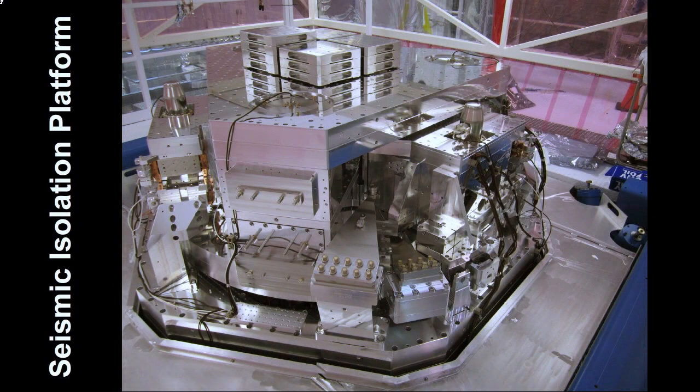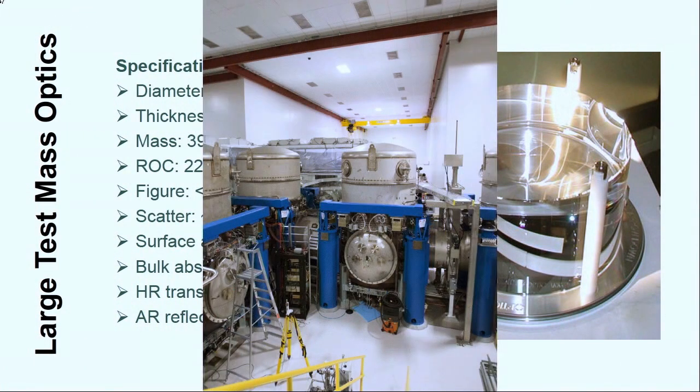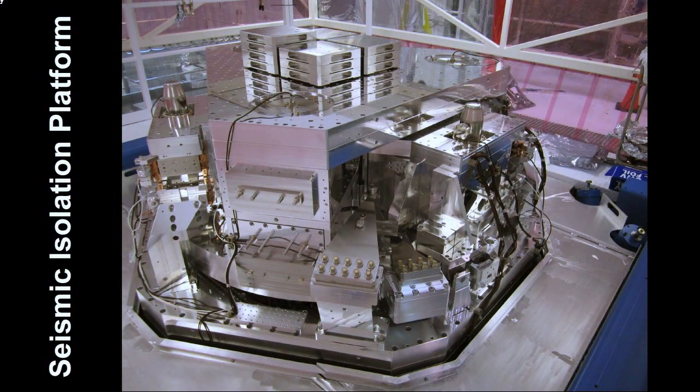This is a seismic isolation system. This quadruple pendulum is not enough to give enough isolation from the ground. It gives us about 5 to 6 orders of magnitude isolation at 100 hertz. We need another 4 to 6 orders of magnitude isolation. This is actually an active system.